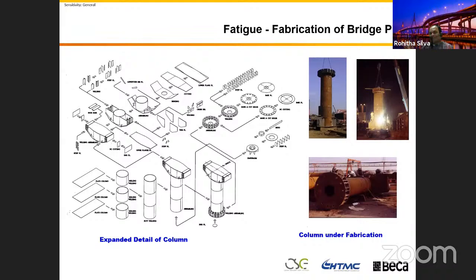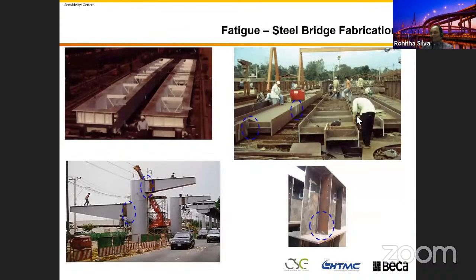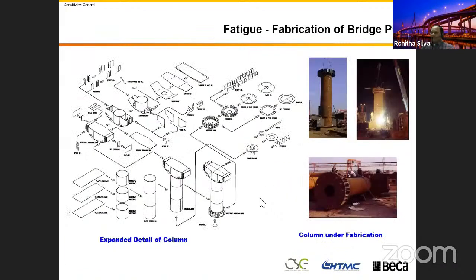So then I know that in terms of design, it's working. But when you come to the detailing, because welding is done by humans, though some welding now uses robots, there are different conditions and different welding environments, and you need to assume those things. The people are welding in a different country, and you can't check each and every weld 100% to make sure that it's all covered. It all depends on the people's experience. You need to think about all those elements when you design and detail your weld.